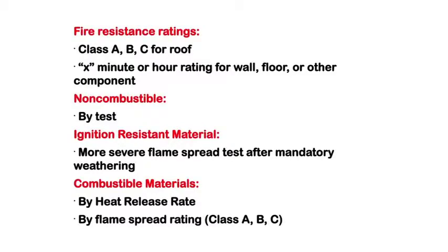Non-combustible: there's a test to describe whether it's non-combustible or not. Things that you have a question about, you should be able to ask the manufacturer. They should be able to tell you and show you test results about the non-combustibility test. It's a particular standard method, and it'll indicate non-combustibility via this test method.